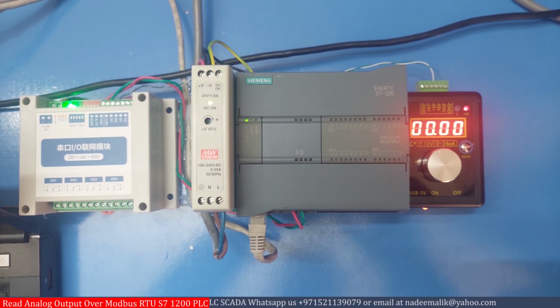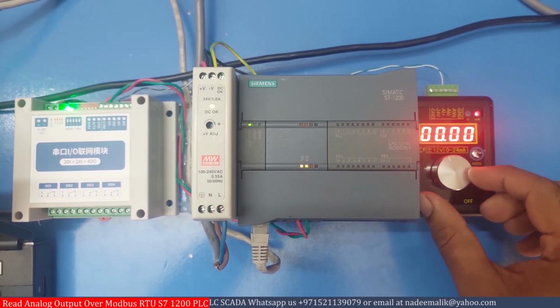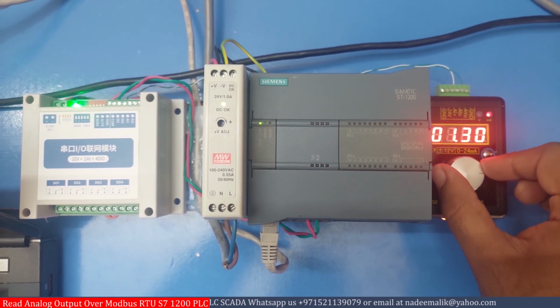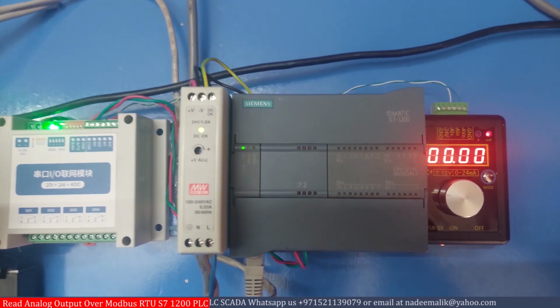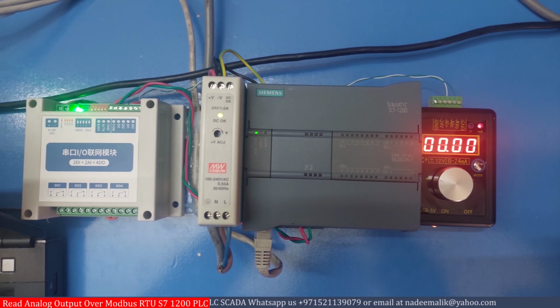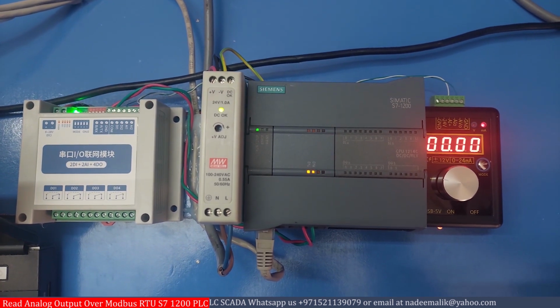Welcome to another training session of the TIA Portal. In today's session, we will try to connect an extension I/O module with the PLC over RS485 communication using Modbus RTU protocol. We have an I/O module with 2 analog inputs, 2 digital inputs and 4 digital outputs. We will connect this I/O module with the PLC and try to read and write the IOs of this module using Modbus RTU protocol.